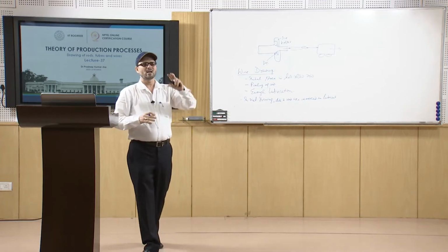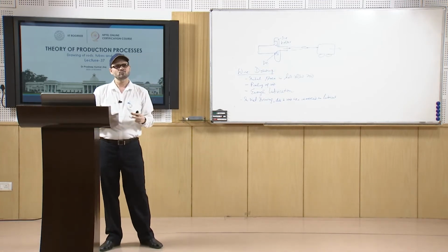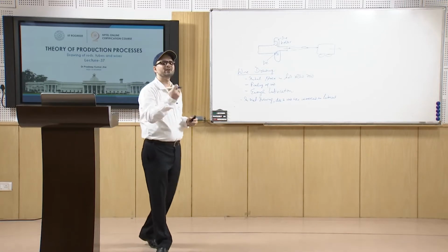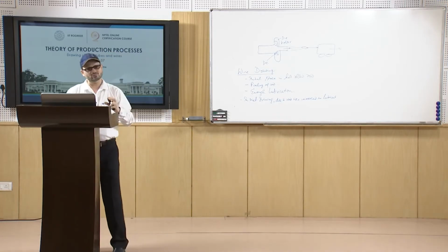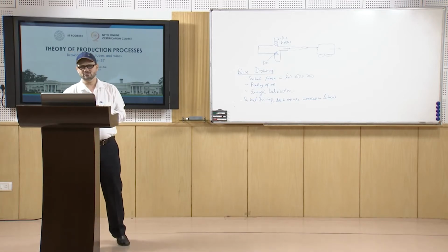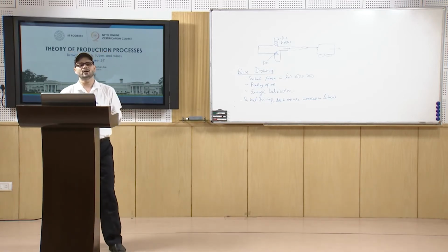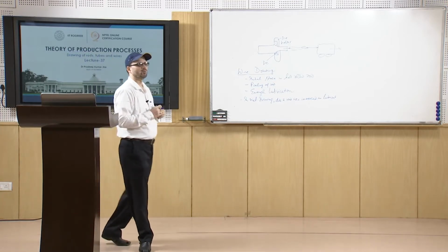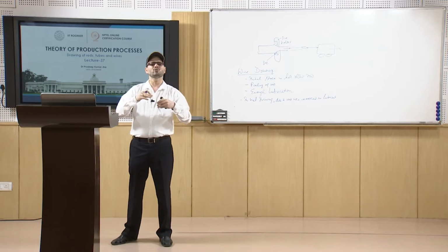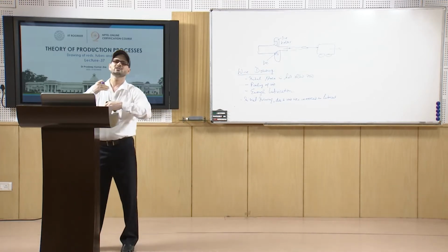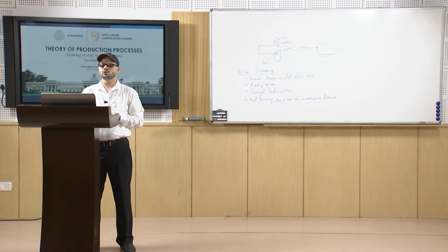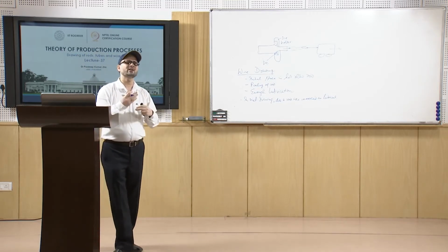Depending upon the requirement and the treatment given, whether you want soft or hard, you make the wires accordingly, and that depends upon what type of metal you are drawing and also the amount of reduction involved.